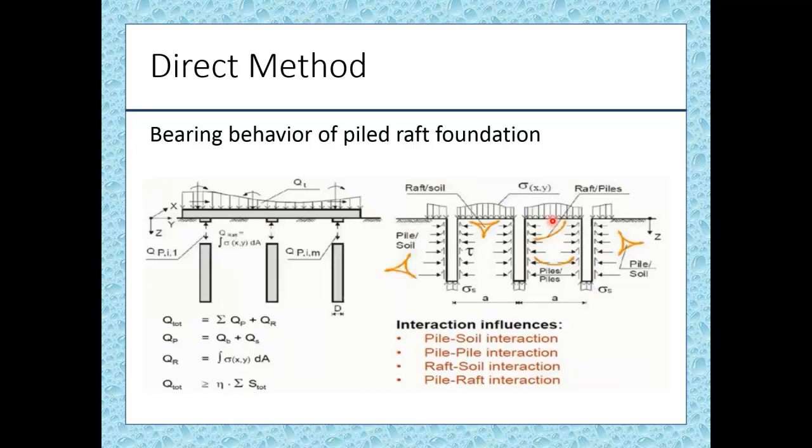And the total combined bearing capacity by the pile raft should be larger than the applied load. Yes, we need to also multiply it by a factor of safety and then compare it with the bearing capacity that we have got.